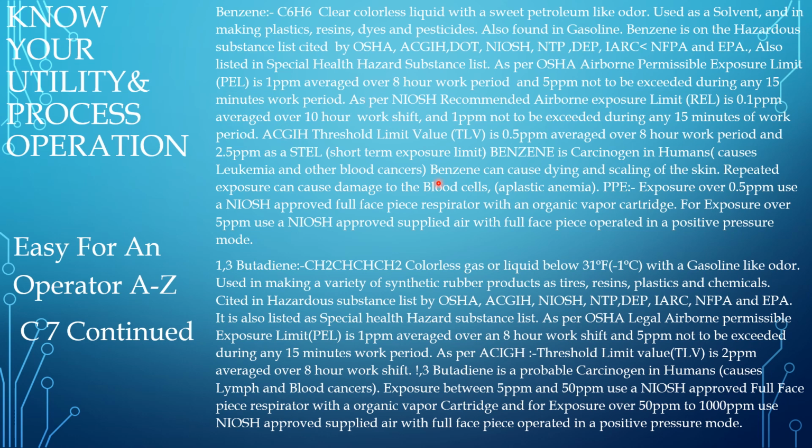Normally in petrochemical plants, benzene solvent is used. The contract laborers who are not technically educated, doing the maintenance job and the cleaning or sweeping work, used to handle benzene to wash their helmets and clothes. If you come across those people in your industries, kindly advise them of the properties of benzene, that it is a carcinogen, and the causes of exposure in a benzene atmosphere. Also try to help them to use this PPE.